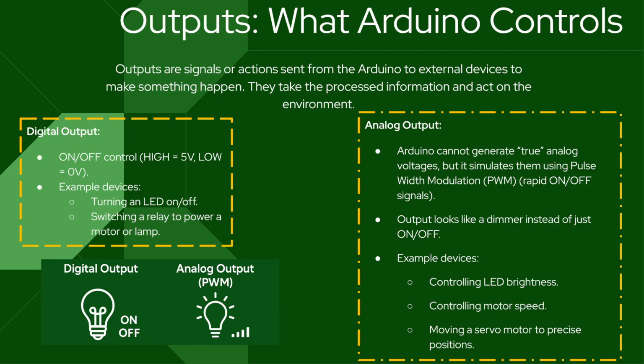And then our analog outputs, this is honestly one of the most important parts. We have PWM, pulse width modulation. This is a rapid-fire signal of on, off, on, off, on, off. This is how we do motor control and how we control the speed. Motors take in these on and off spikes, and the lower the spikes, the lower the speed. The higher the spikes, the higher the speed the motor is moving. So we can use that to control a whole bunch of different things. Again, the best example is a motor.